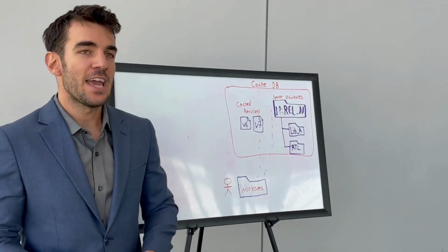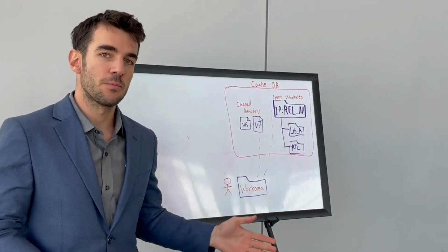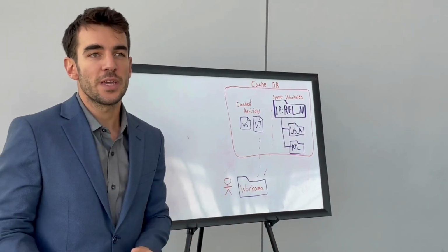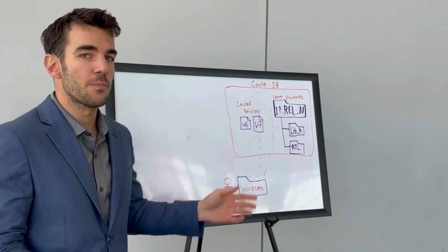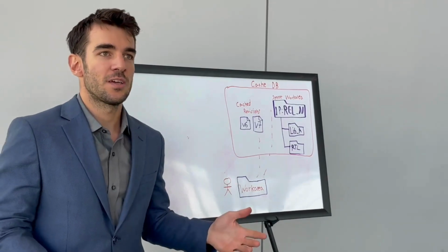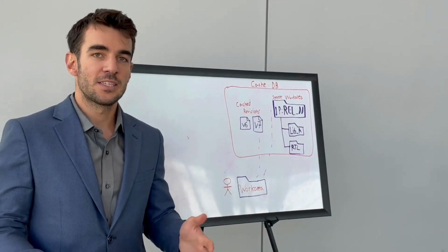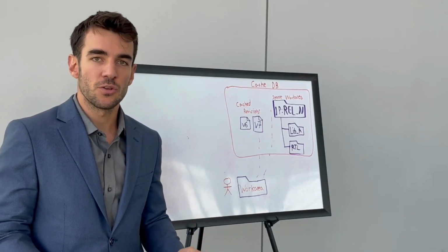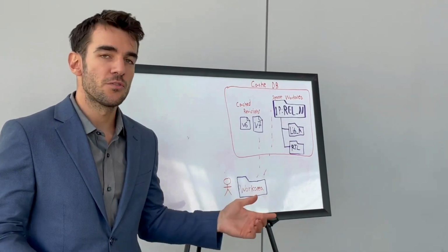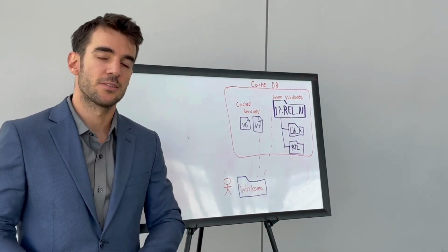So user A might be a consumer of this IP, so they will be sparsely populating the IP in their work area, but user B might need to tweak it, so they would be populating this IP in the traditional links-to-cache approach. Again, not consuming extra disk space with the links to cache, but the sparse populate is optimizing the population, the sync to the repository, because it is a single link pointing to the IP instead of tens of thousands of links pointing to the individual files.